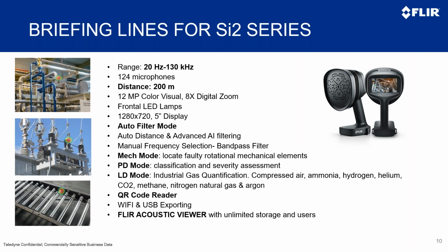We have three main modes. Mechanical mode for faulty rotational mechanical elements, PD mode for finding, classifying, and assessing, so giving the severity level of the partial discharges, different kinds of partial discharges, not only corona, any kind of partial discharges. And we have leak detection mode for compressed air and for industrial gases. As I said, the camera finds any kind of leak from pressurized systems of any kind of gas.